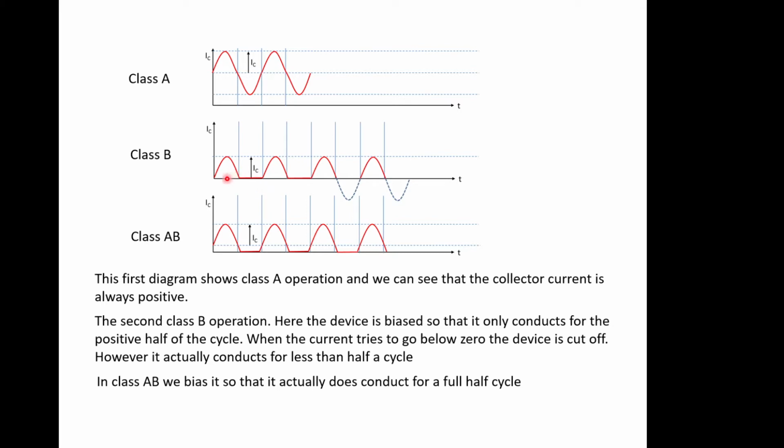Now, it's never as perfect as this, because you always need a small amount of voltage to turn on a transistor stage. So although it's been drawn here as having a good joined up sine wave, there's actually what's called crossover distortion at the zero signal input point. So there'll be a little step, just as this one is, say, turning off, but this one just hasn't quite got enough voltage to turn on yet. It needs 0.7 volts of input before it starts to go, so there'll be a little bit of distortion here, and we'll look at that.